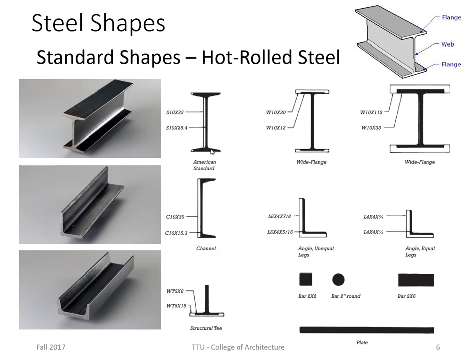We have an American standard beam, okay? And you'll notice one of the things, this is called a wide flange beam. In this diagram, it's showing you that a 10-inch beam may have different weights. This number here implies a weight. So the smaller web here, this is called the web, this is called the flange. And you can see the difference, the range, and even the height of a 10-inch beam.